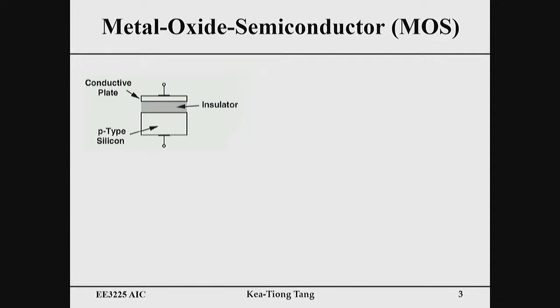And we say that the MOS transistor, the basic structure is a capacitor. This capacitor has two conductive plates. One is poly, which is the gate, and another plate is the semiconductor, which is lightly doped p-type silicon. And actually, we form a capacitor as a structure.